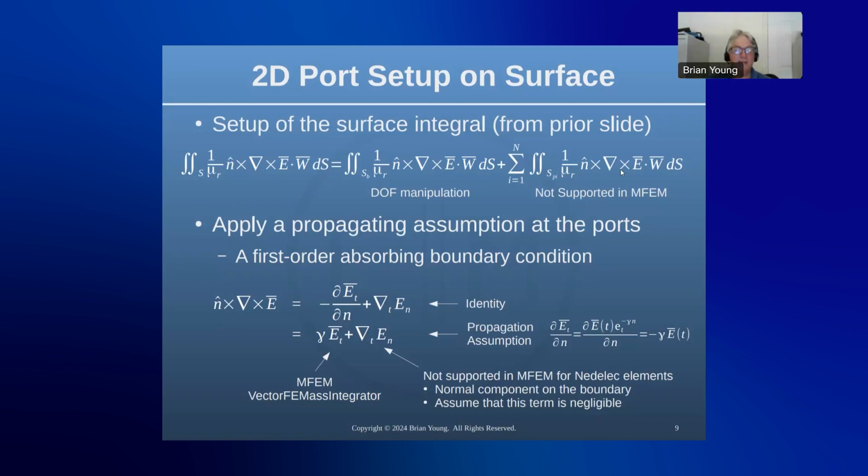So that's in effect implementing the first order absorbing boundary condition. Right. So when you use gamma for one mode, say the odd mode, you'll be matched then. But for the even mode, the gamma will be slightly different. So you'll be slightly mismatched for the even mode. And so that will distort the solution slightly. Right.